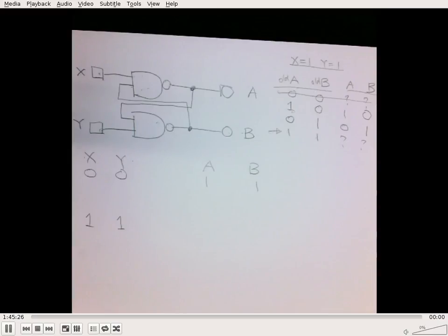Logician will tell you it is going to oscillate because it is basically having 2 possible paths of state change, and both of those are possible depending on which one switches first. But it's not going to oscillate. Because once you settle to one being 1 and the other one being 0, it becomes a stable state, and it's not going to switch again.